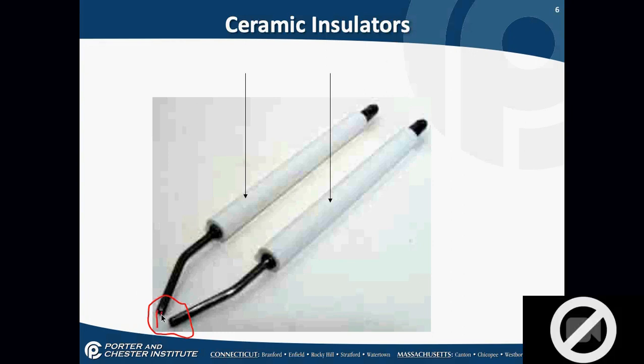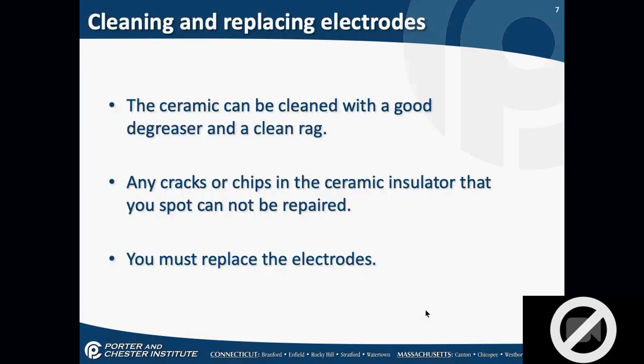New tips will actually come out to a point. They have a really pointed end on them. So these tips are actually worn a little bit. Actually quite a lot. This is something that when the tips get to this point after a couple years, and these don't look like shiny metal, even though the picture's not all that great. As these tips wear down, sooner or later you have to replace the electrodes. They're universal. They're not tough to replace.